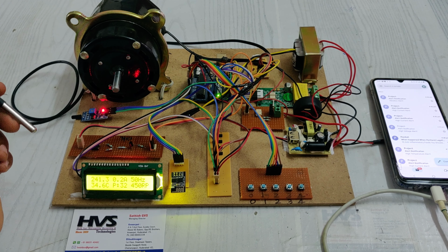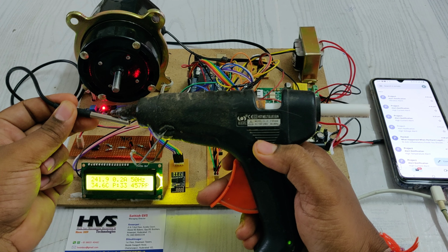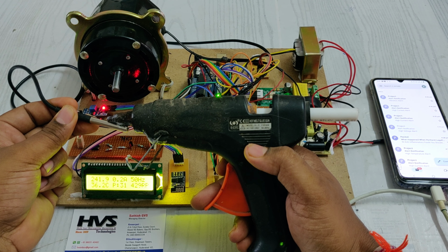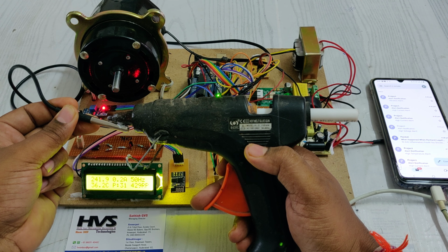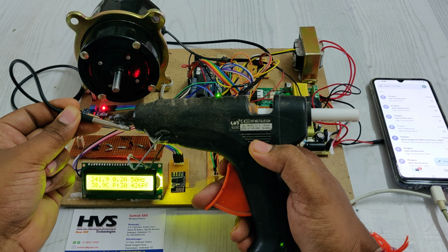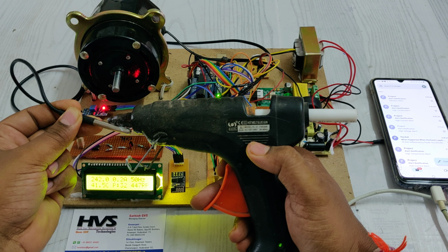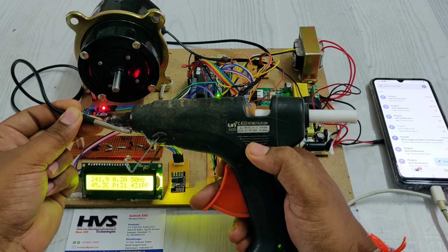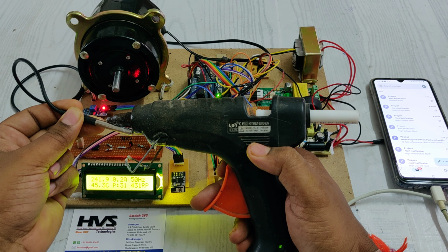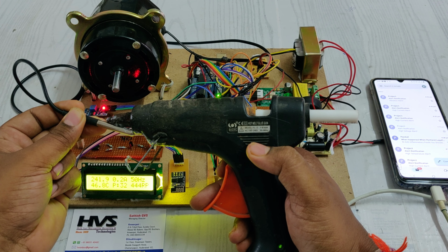And coming to the temperature, we are increasing the temperature now, just using the heating object. For every 2 seconds we get the updated details on the LCD, and every 10 seconds the system uploads the data to the Thingspeak cloud platform. These threshold values we can change in our program to get faster email alerts with lower threshold settings. Whenever the temperature crosses 50 degrees centigrade, the system will provide an audible alert through the buzzer as well as a message alert on the LCD. We can see that.